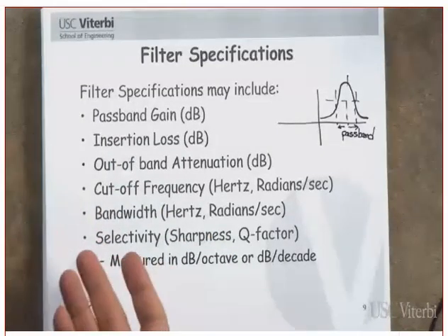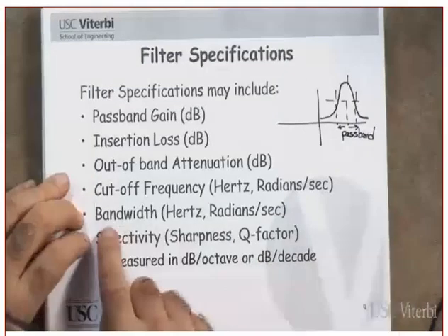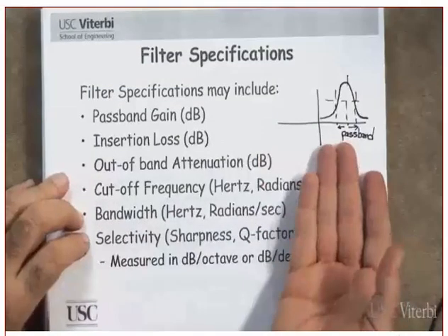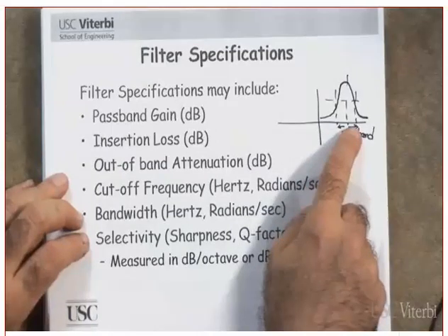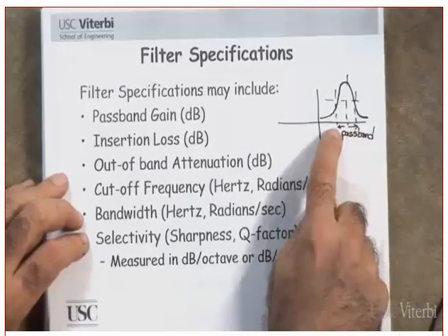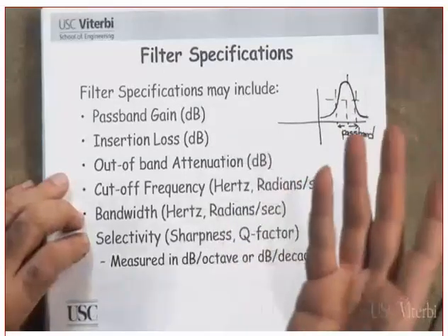If the filter happens to be a passive filter, then the maximum gain is 1. So we say the 3 dB is 0.707. Clear? Okay, keep that in mind. The bandwidth, how do I measure the bandwidth here? For this one, the bandwidth is, for example, F high, F2 minus F1. We call it a 3 dB bandwidth. That's the 3 dB bandwidth.